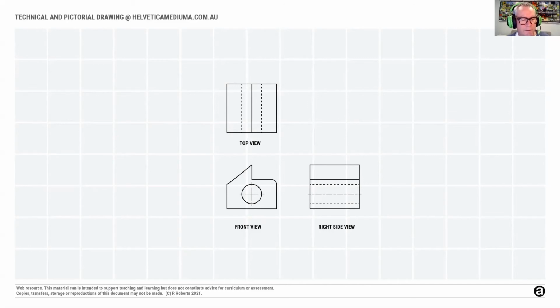If you look carefully, you'll see three different kinds of lines: thick, continuous lines for outlines, thick, dashed lines for hidden details, and thin chain lines for centers. Different kinds of lines are part of the Australian standards conventions we follow in VCD.